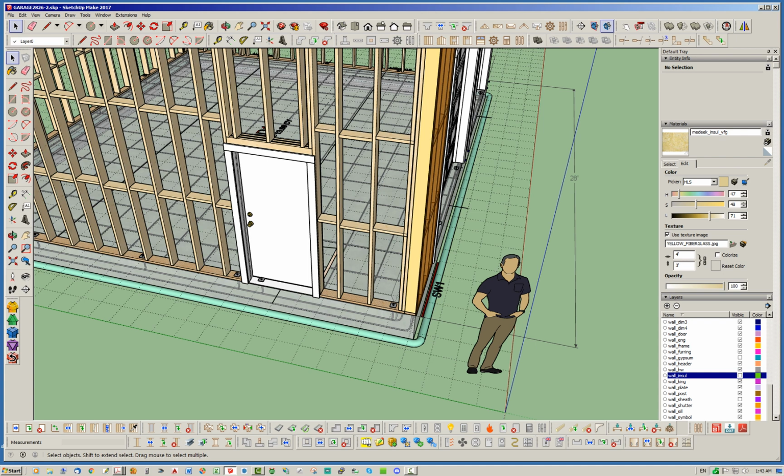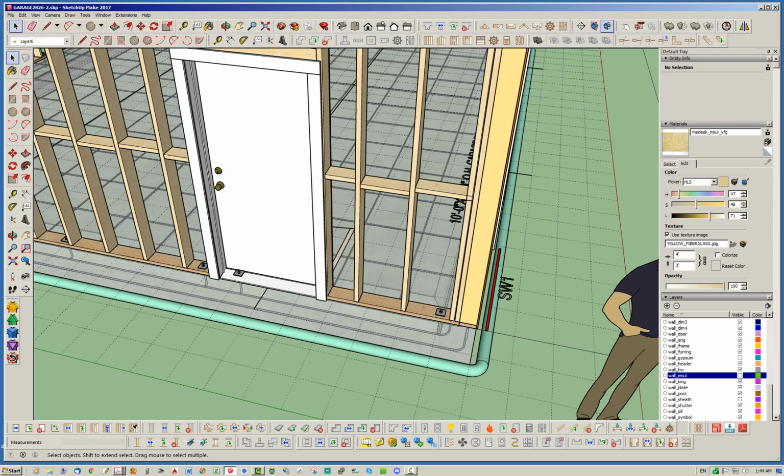So if you're going to make certain manual edits, like subtracting certain geometry, what I suggest is to wait until you're at the very end of editing that assembly, and then you can make a few last minute minor modifications. And then of course, if you don't edit it again with the plugin, then you have what you have. So we're breaking the parametrics a little bit by having to move some of these anchor bolts around, but that's really the only major one.